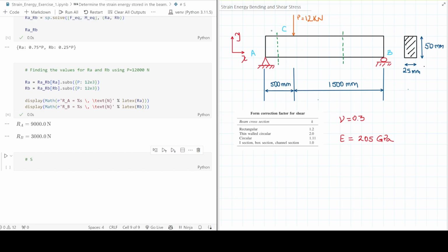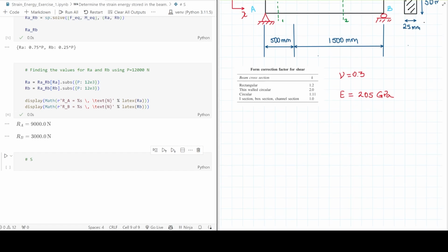So I could call this section 1, and section 2. If I want to calculate that shear force diagram, I just make a cut here and I see how much the reactions are here. But let's do it. So let's use this instance that we have here. If I have a piece of beam here, something like this, then I know that here is the support, and this is the cut that I have just done. This is 1, 1. And let me delete this because I'm going to substitute it by the reaction force in A here.